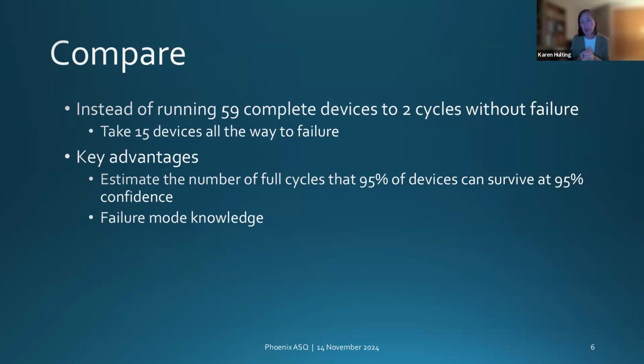There is a question in the chat, I see, differentiating between reliability test approaches for disposable versus multi-use products. I would say the main difference is that it can be more difficult to fund more expensive, longer-use products. All of the same topics apply. It's just that in the case of disposable products, I feel like we have no excuse for not doing this cycles to failure testing.